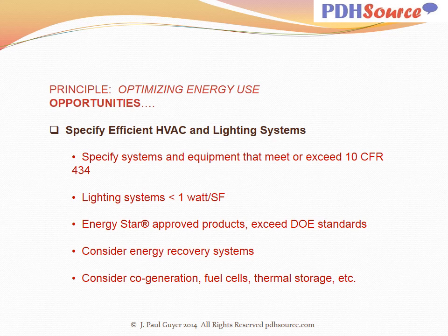Now that's when you had a large percentage of incandescent lamps. But with the improvements in energy efficiency of the lamps that are now used in interior illumination situations, fluorescent, and some of the even more exotic lamps, that rule of thumb is now down around 1 watt per square foot. So that's been a big improvement, and it's just due to improvements in the industry and the products that are made available to the building designer.